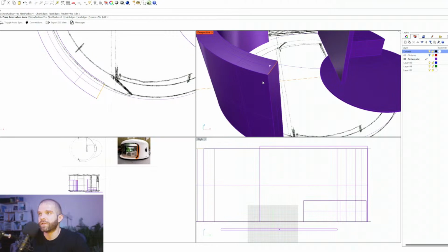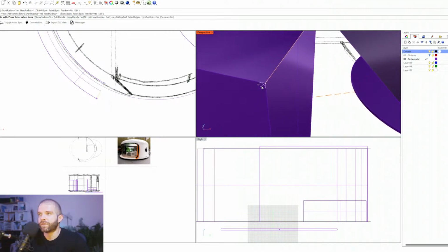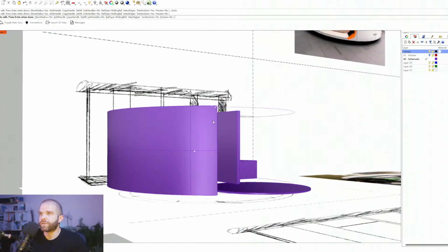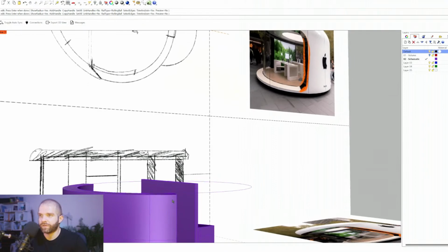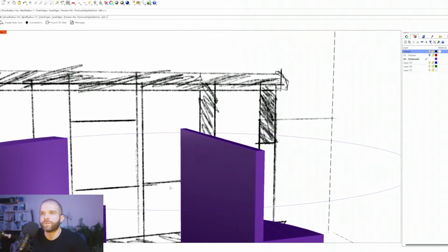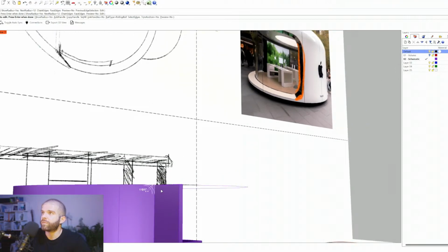Select edges to fillet. So it's doing 1 inch, which if I see the preview there on the side is way too small, right? So we're just going to eyeball this from our reference. I'd say it's even almost like a foot. So we'll do next radius in the command, 1 foot, or 12 inches. That's closer, but I think we still got to go bigger.